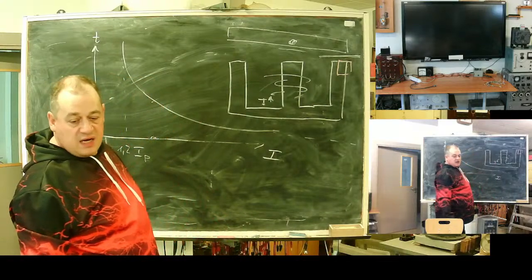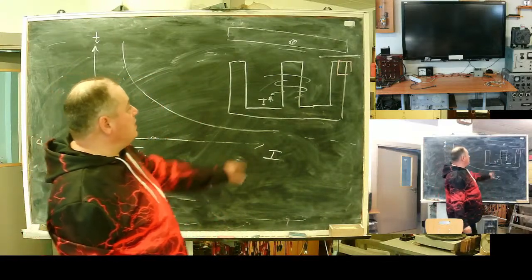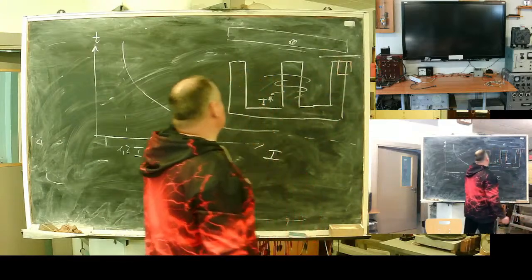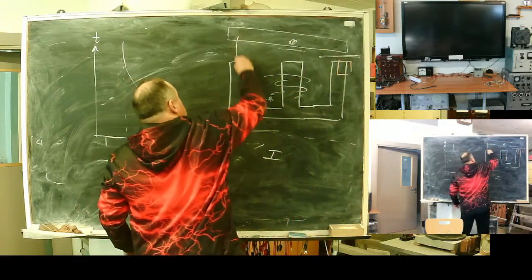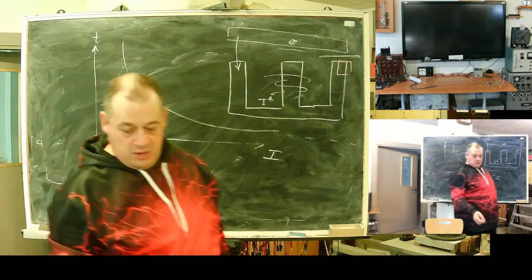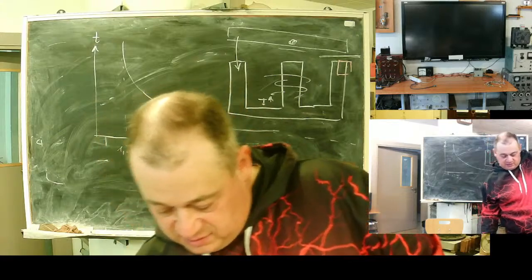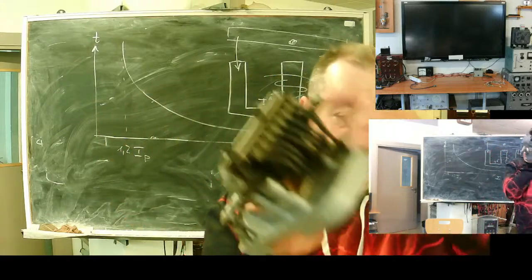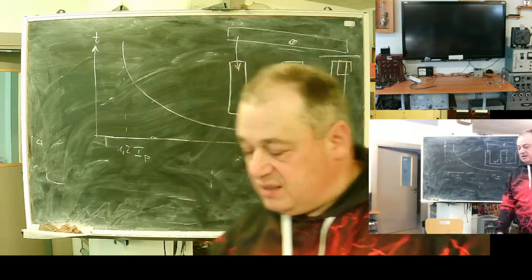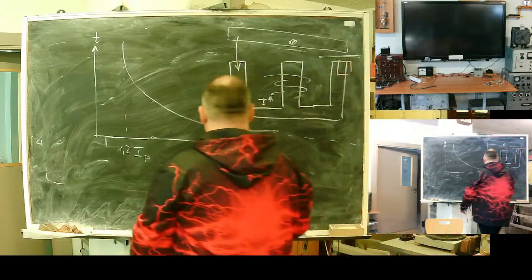While currents are relatively small, only this part works. And this rotates, counting time. But on high currents, this part triggers instantly. It causes instant operation with this adjustment screw. You can select an instant trip time.